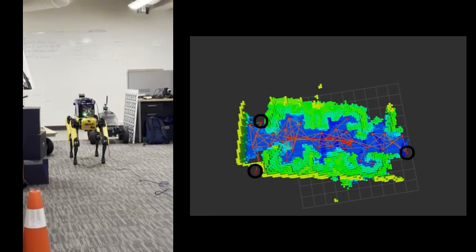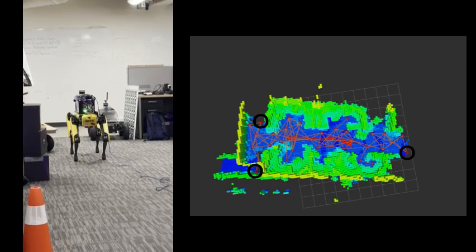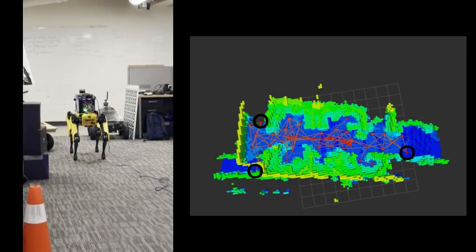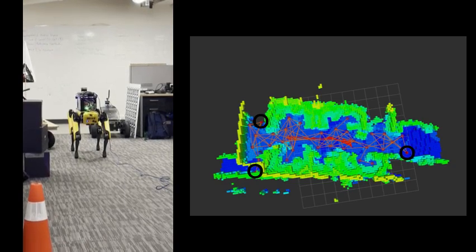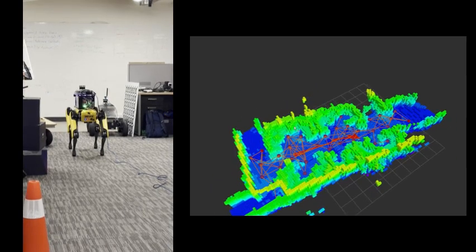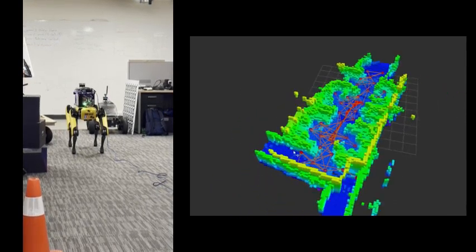Once the points are identified, SceneSense begins predicting occupancy at range. 5 predictions are made at each point and merged into the running occupancy map as they are produced. The resulting map is shown here, with extended geometry that could be used for robotic exploration or navigation tasks such as planning or path selection.